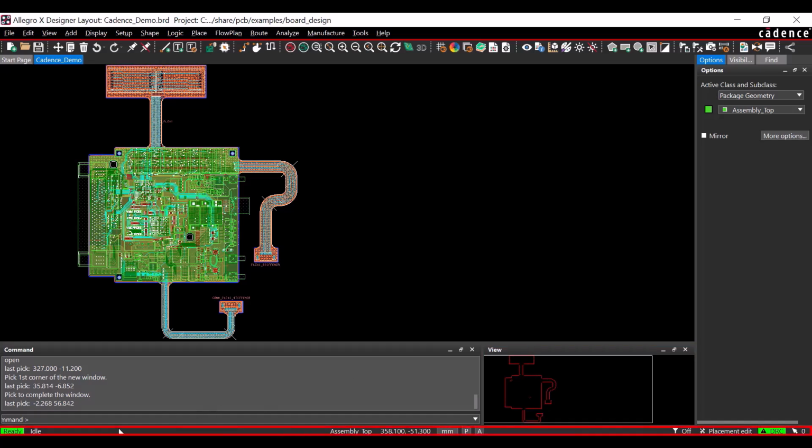This has several fields. The first one is basically a red light. Green means everything is good, the system is communicating with you and you can go ahead and proceed. Yellow indicates the process is being run, but you can interrupt it. You can hit the escape key, or there will be a command inside where you can click the stop. Red means there's a process running and you cannot interrupt the process, so you have to wait for the process to end before you can continue.